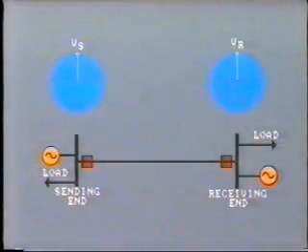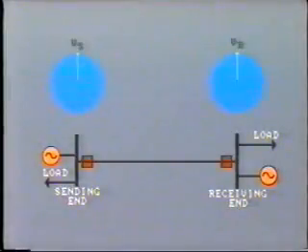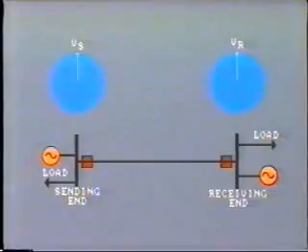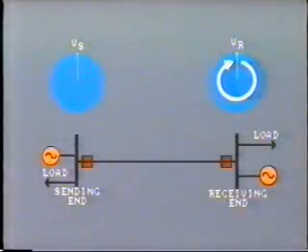All this has happened in about half a second. The turbine governor has hardly had time to act yet, so the generator rotor continues to accelerate. Looking at a specific case, this transmission line has the sending end voltage fixed, with the receiving end voltage allowed to rotate. VR is equal to Vs. Under an out-of-step condition, the locus of VR is a circle.